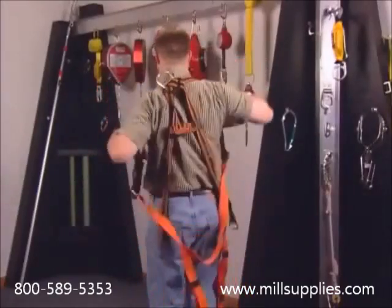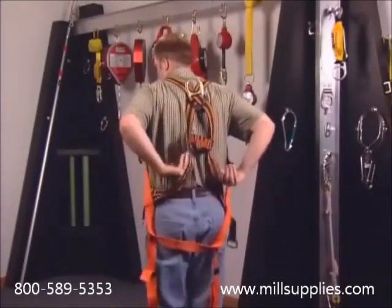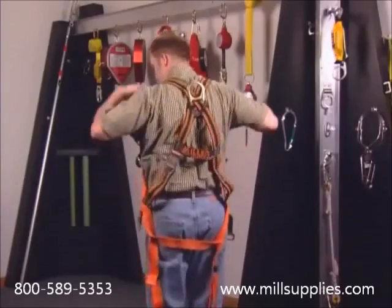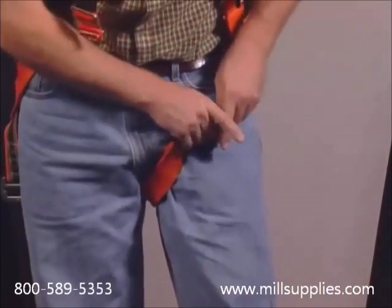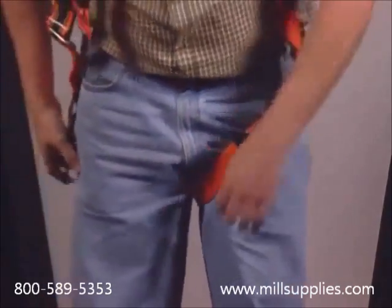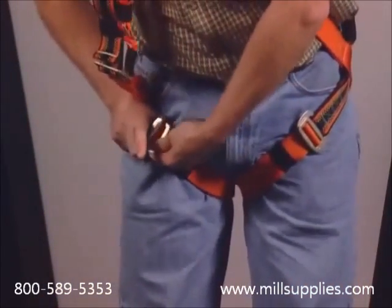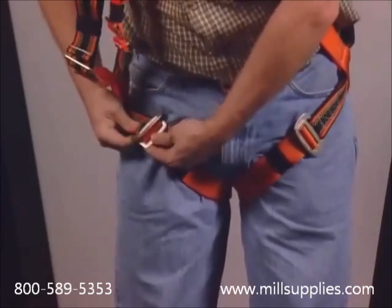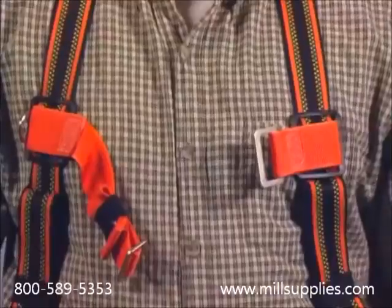Slip the straps over the shoulders so the back D-ring is located in the middle of the back between the shoulder blades. Pull the end of one leg strap between the legs and secure to the opposite end. Repeat this step with the other leg. Connect the waist strap if the harness has one. This should be tight but not binding.